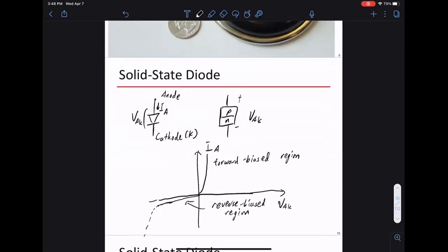And then often for the forward bias, you'll see this sort of 0.7 volt drop. Right? For us, 0.7 volts is almost never important. If you do VLSI design, then 0.7 volts is significant. A lot of applications depend on this 0.7 volt forward bias, but for us, we don't. 0.7 volts is not going to matter when you're talking about tens and hundreds of volts. So for us, we'll pretend the diode just turns on immediately once it's forward biased. We'll often ignore this 0.7 volt drop. Any questions about the diode?